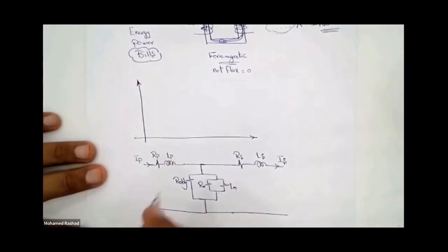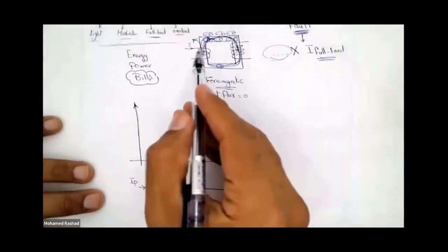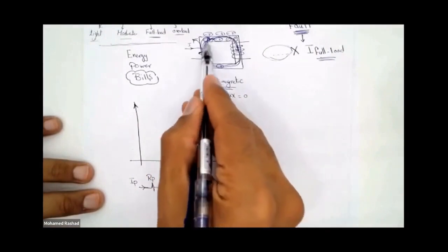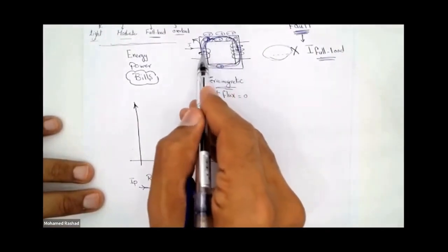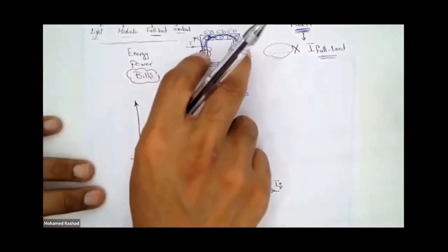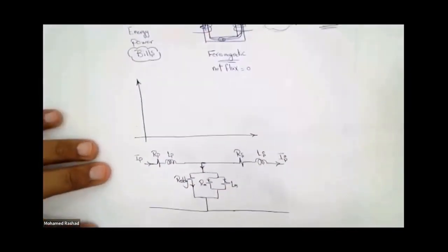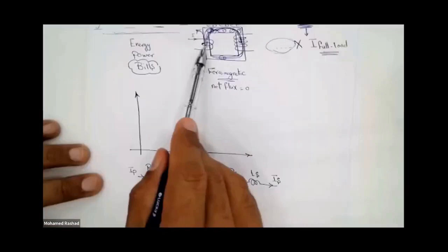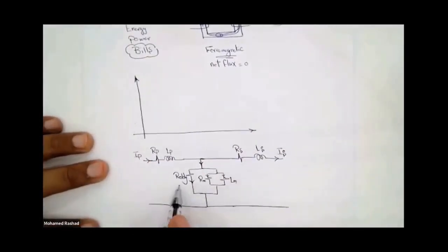Good. Regarding my transformation, part of the magnetic field transforms into eddy currents, and another part is used where? It is used in the magnetization of the core, meaning the magnetization aligns the dipoles inside the core so that flux starts moving from the primary to the secondary circuit. This is the topic of core magnetization itself, which involves the currents being drawn here.